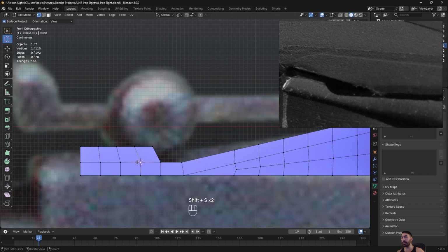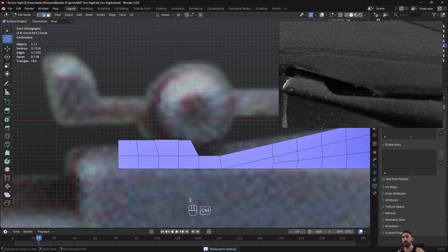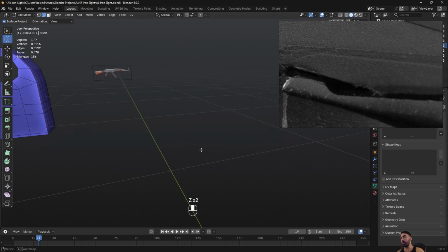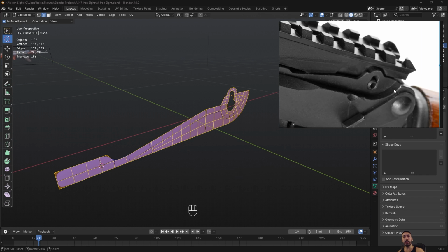and I'm also going to make this a lot nicer by doing this. Check this out. I want to make these edge segments here completely straight, and to do that I first have to bring this vertex forward a little bit, and then I can use my loop tools down here to make all these edges straight. So I do Loop Tools, Space, and there we go. That's beautiful.